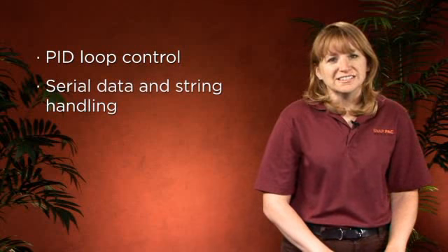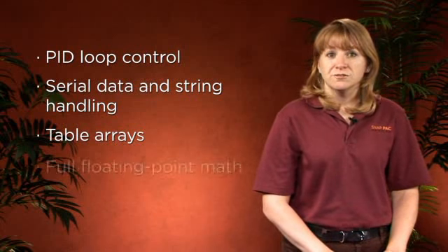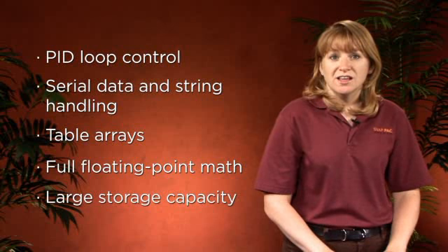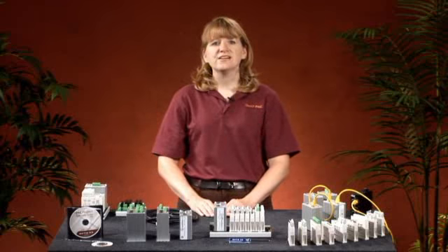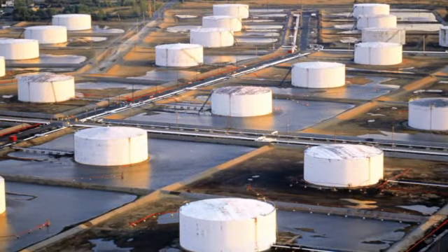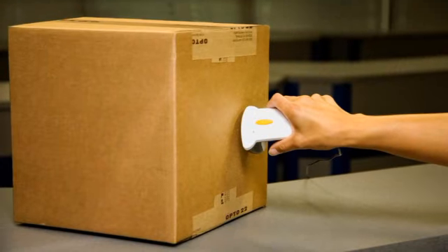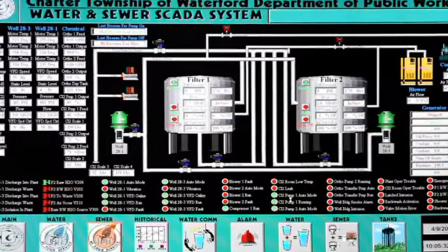It's important to understand that PACs are much more than a traditional PLC. Like PLCs, they can handle everyday control and automation tasks involving digital and analog I/O. But PACs go further by including sophisticated PID loop control, serial data and string handling, table arrays, full floating point math, and they're capable of storing large amounts of data. Plus, PACs include built-in Ethernet networking and serial ports for use with modems. Because of all this functionality, PACs are ideal for process control, sequential logic, barcode and RFID applications, SCADA, motion, and much more.